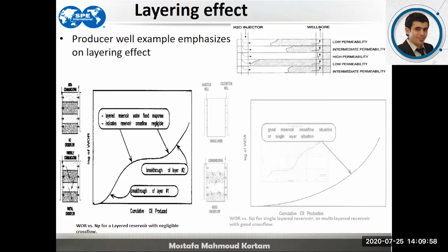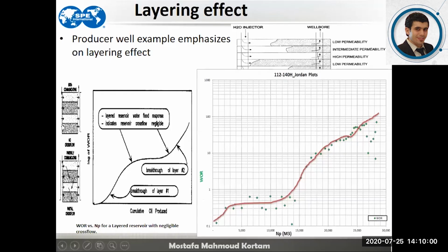So investigating the water oil ratio for a particular well, it fits the performance of the log water oil ratio. A breakthrough has happened in one of the layers that this well is penetrating, and that was a time when there was some increase in the water. It is also worth mentioning that the well is producing with a high water cut.